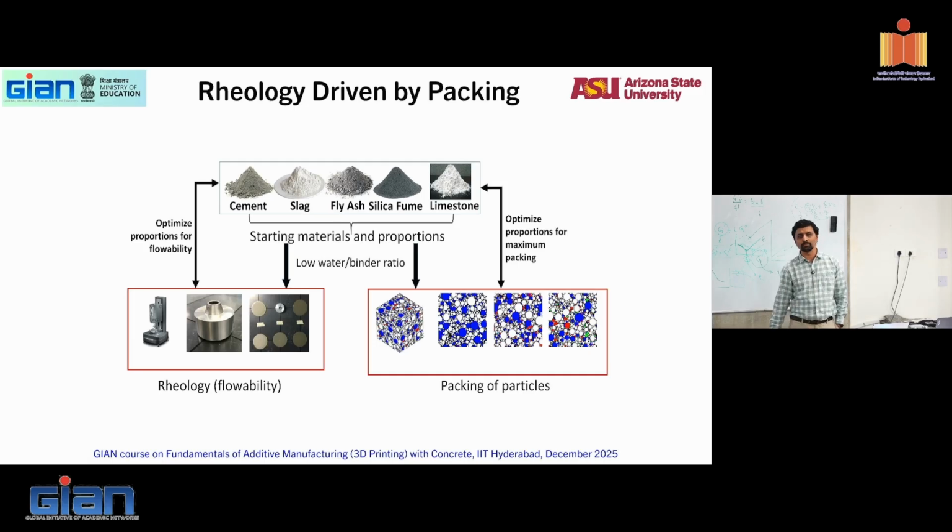One is a complete cement-based mix that we print at 0.4 water to binder ratio, and the L30 mix, a 30% limestone mix, which we print at 0.35 water binder ratio only. This all goes down to the packing, the actual gradations of particles present in the system. So it changes the amount of water required also.